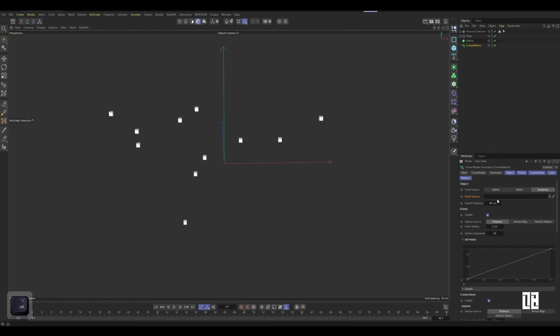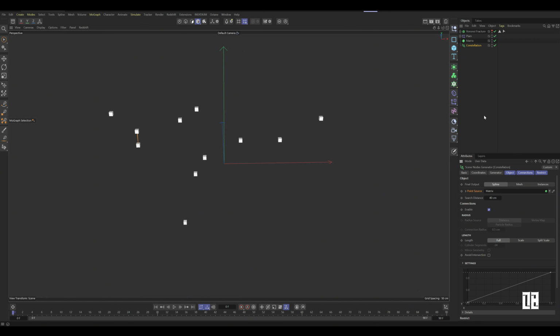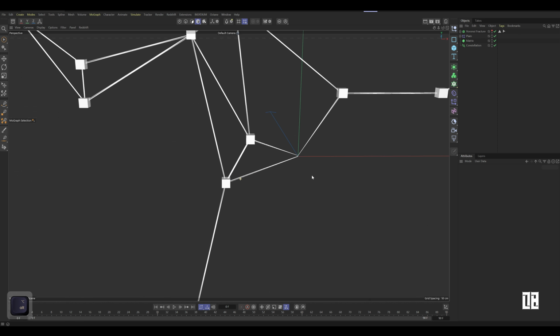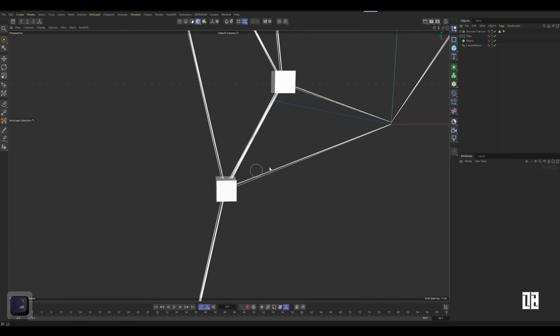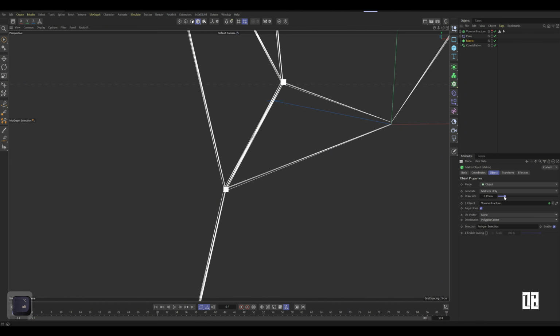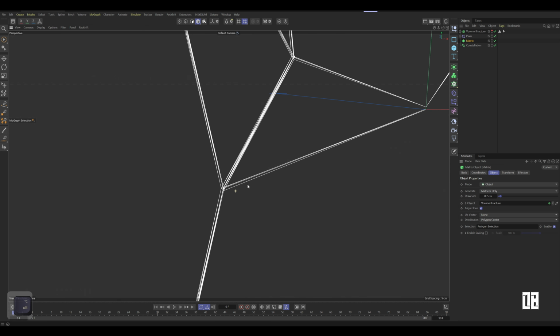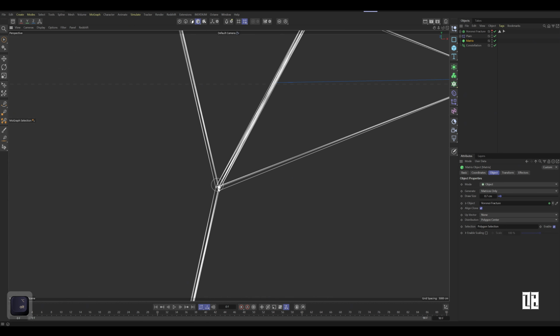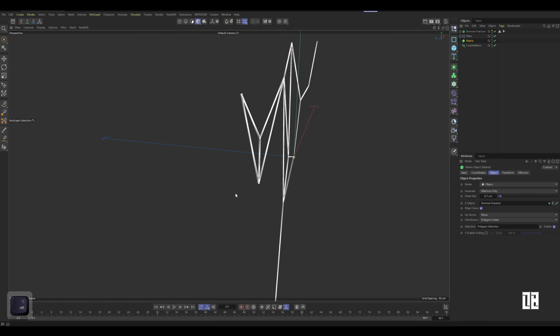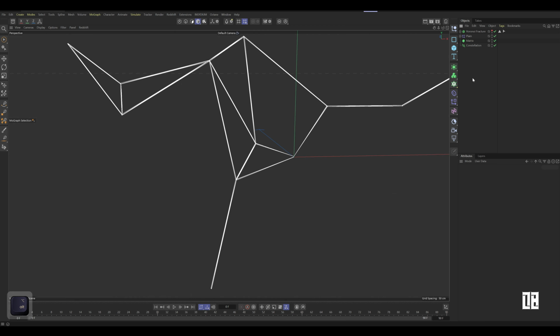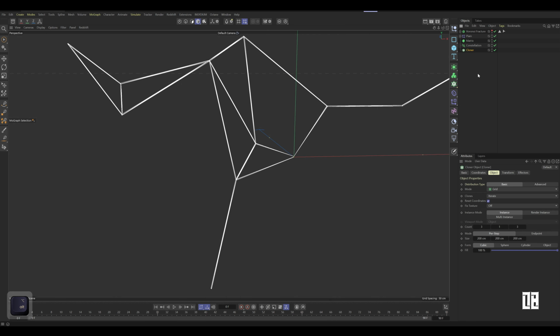Select the constellation object. Point the source to the matrix object. Switch the final output to line segments and adjust the search distance. A closer look reveals that each point generates several sets of lines, which is not what I want. After my research, I can't use matrices as point sources. The problem can be solved by cloning a single point.